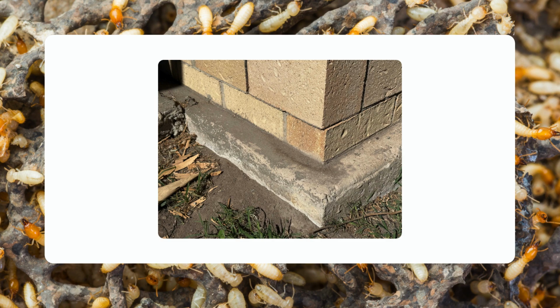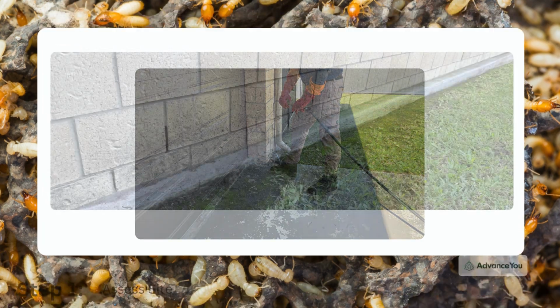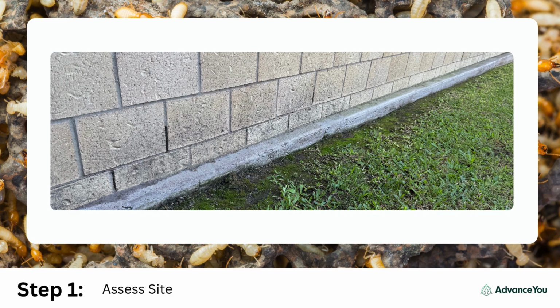In most cases, an exposed slab edge is a sufficient termite management system in conjunction with annual timber pest inspections. However, in this case, the driveway bridged over the exposed slab edge, and then the garage required protection via chemical treatment. Before beginning a chemical soil treatment using the trenching method, you should carefully prepare the worksite.